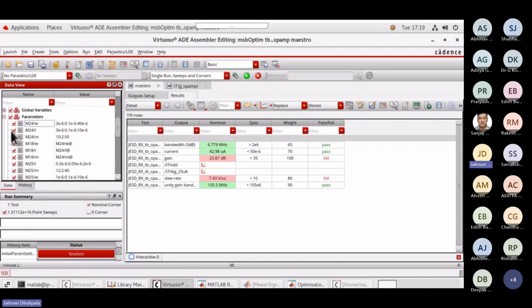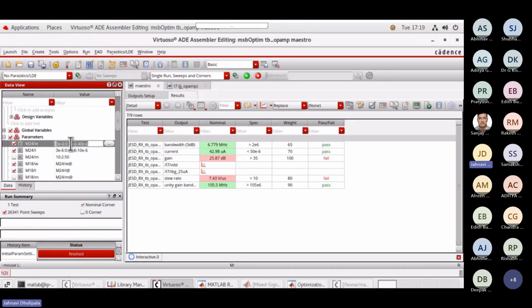So in the next 10 minutes, we will also see how we use MATLAB to help us automatically scale these dimensions. Here we take these values, and we also mention the dimensions of the transistors in such a way that we meet our constraints and our optimization objectives, so that when we apply these computed width and length multiplication factors, we actually meet all our specifications.